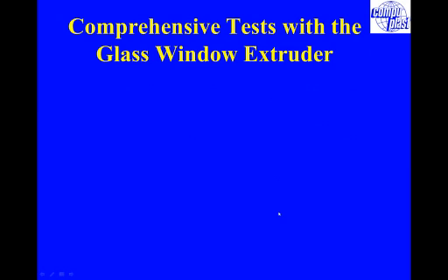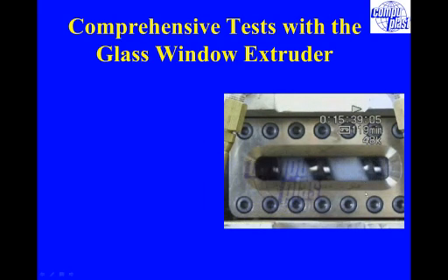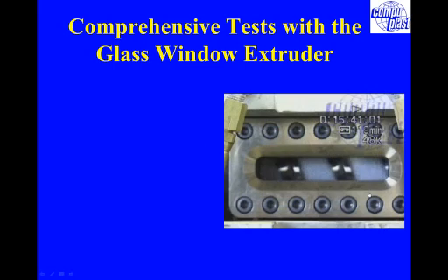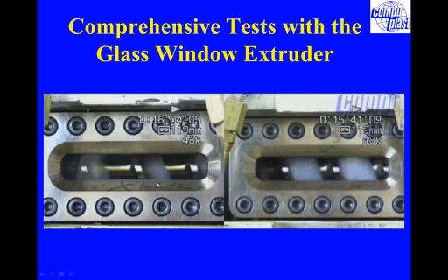Now let's zoom in a little bit on another window here. So here we see the solid bed, and I'll just pause it for a second, right there. Here's the solid bed, and here's the melt pool in the screw channel. As you proceed along, you see the solid bed gets narrower, and the melt pool, of course, gets wider to accommodate the molten polymer. And over here on this side, what we'll notice is that the solid bed is discontinuous at some points. You can see it disappears.